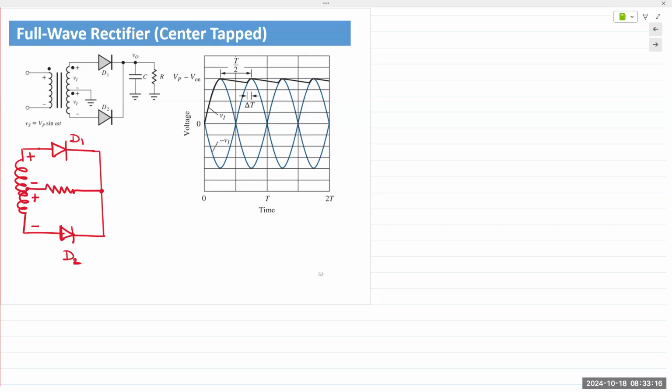So in this example, the question being asked is how would that transformer work, or how does a tapping work, right? Tapping is basically you're just taking an output in there. So you're splitting the secondary coil into two parts. Now, that depends on the number of turns and the turns ratio and all of that. So it depends on what output we want. In this case, we are simply saying that the secondary coil is divided in exactly half.